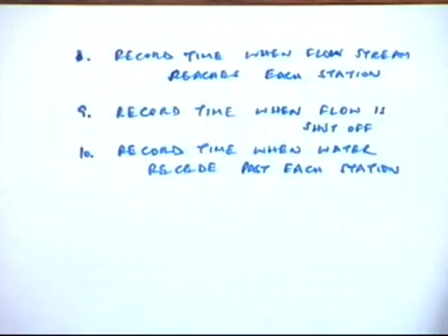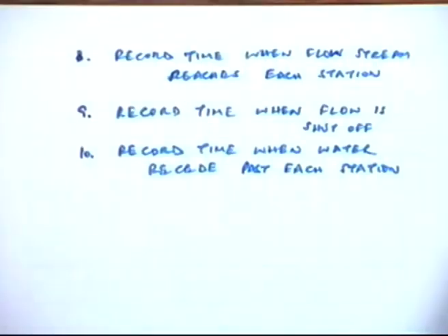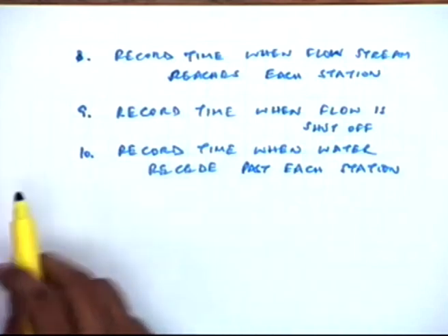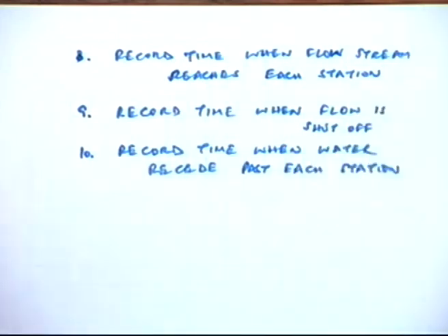In many situations, the water is taking some time, there is some local depression and it is just standing there, and you might feel that it is standing because of that storage which has built up. So that is not exactly so. In those situations where the flat slopes are prevailing, the recession curve might be a problem to a certain extent, but then with experience you will know how this has to be recorded.